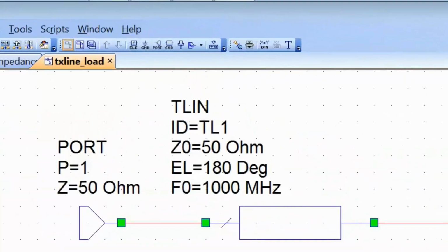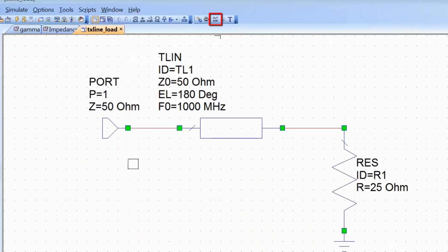Now we'll insert a variable here, and we call it EL_range, and we'll give it a value of 0. This value is completely immaterial. I am just defining a variable which I will then sweep, and I have to, because of the way the simulator works, declare this variable separately and give it an initial value. Then I can connect it to the sweep element, which we'll get in a moment.